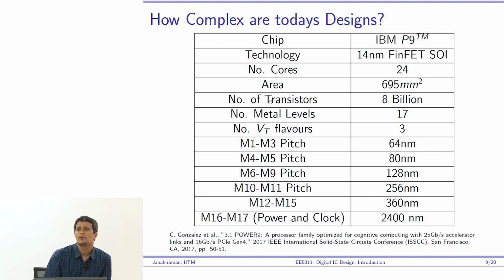Yeah, you have 8 billion of these transistors leaking a nanoamp each, which means very quickly we are leaking amperes of current, right? And what does leaking mean? It means that my device is not in use, it's not doing anything, and in spite of that, I am losing amperes of current from my power supply. My battery is getting drained that fast, or it's drawing that much power, and therefore it's a big problem.